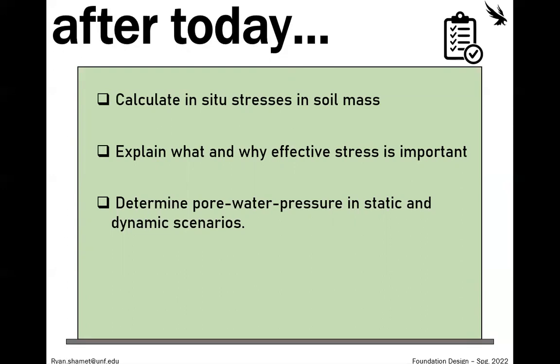So especially in Florida, this is really important. We have a groundwater table that's really easy to find, right? You just go out in your backyard and dig a hole, you'll find the groundwater table. We also have an aquifer system, which is really helpful because that's where we get our drinking water, but it also induces seepage vertically through the soil.